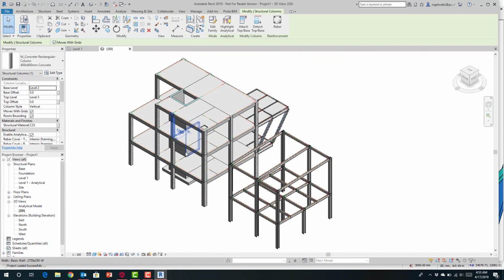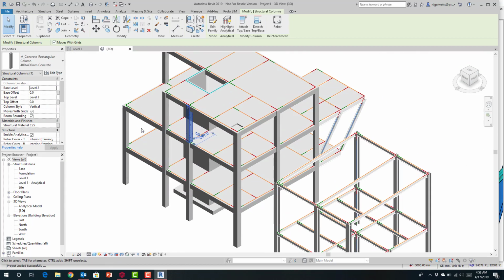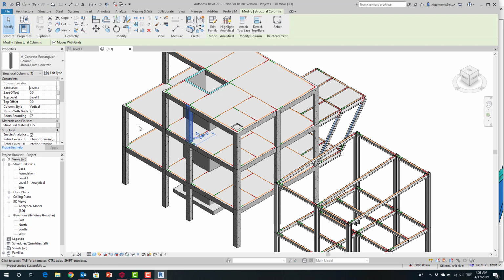Once you're in this environment, you can make changes. Just note that when you are modeling in the Revit environment, you need to make sure that the elements you create are set as structural elements. Walls and slabs, for example, must be designated as structural. We also recommend that you use grid lines to help you with set out and the like.